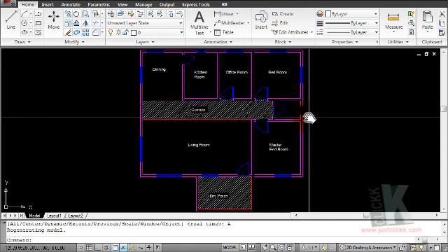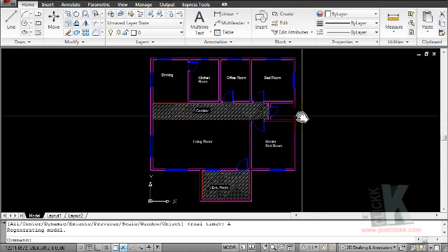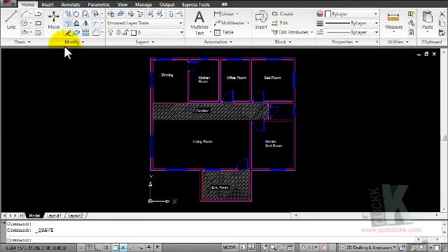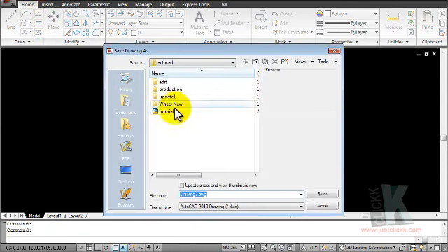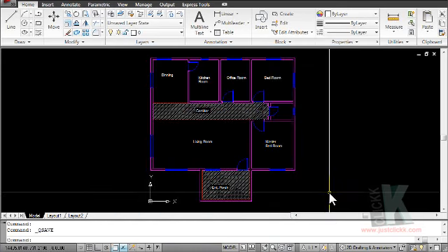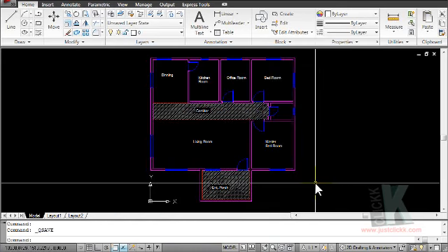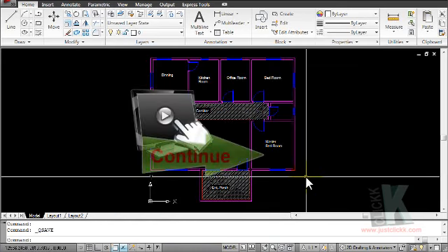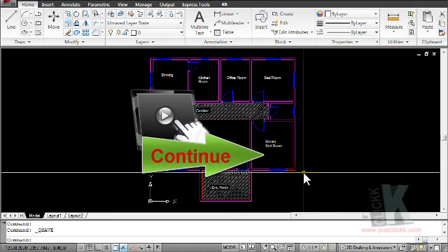Okay, so this is ready, so you can now save this drawing somewhere in your computer. So let's mouse over to the save button. We'll save this. A dialog box comes. We'll type the name, for 3D model. For 3D model, that's the file name. We'll now save. Alright, we have saved that drawing. So let's switch back to ArchiCAD now and import this drawing.